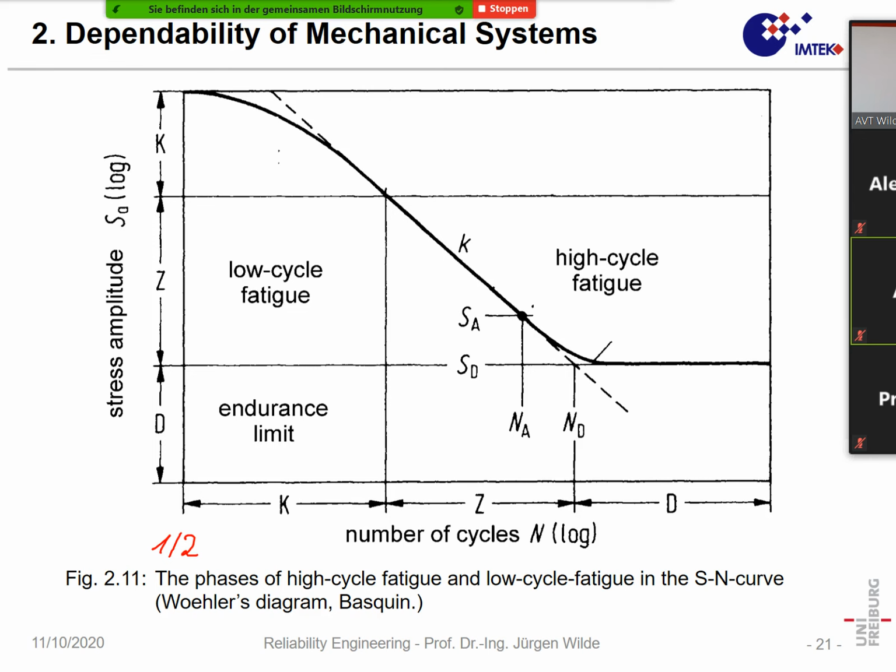we just pull it. It is not really fatigue, but the stress level can typically not be higher than the yield stress. So here we have half a cycle, here we have a log cycle, and then from the yield stress it goes more or less in a linear curve when we have the stress amplitude here, either in a linear or in Basquin in a logarithmic way, and here we typically have 10 to the power of 7 cycles.